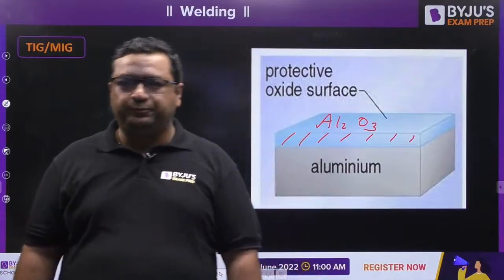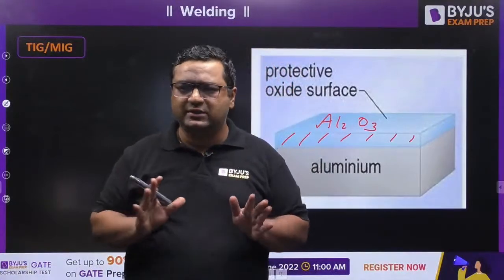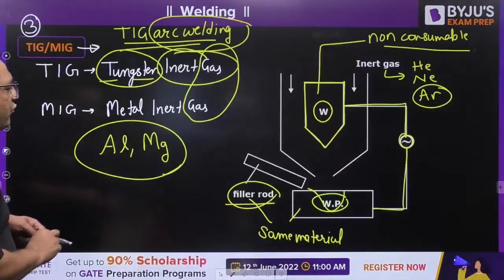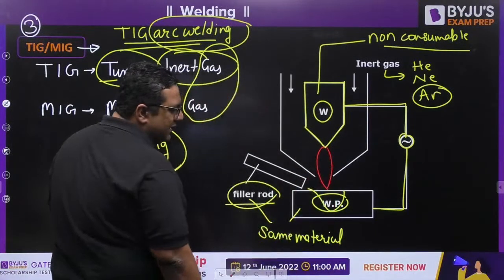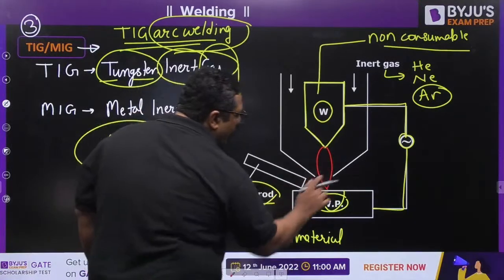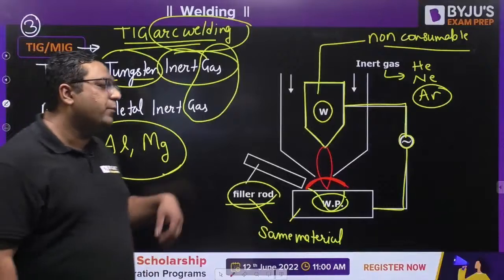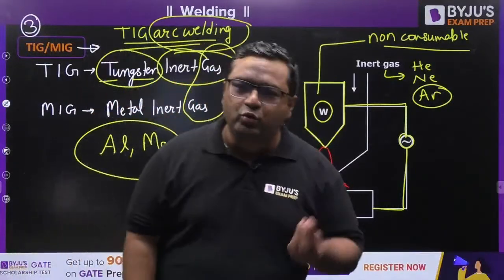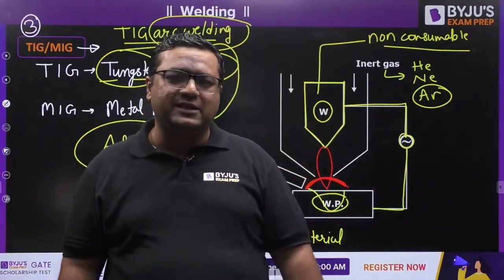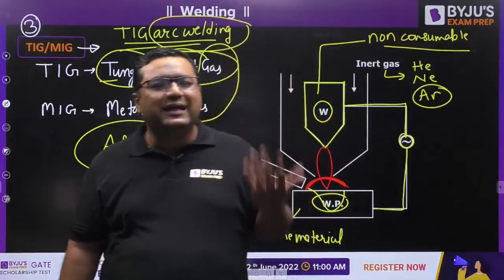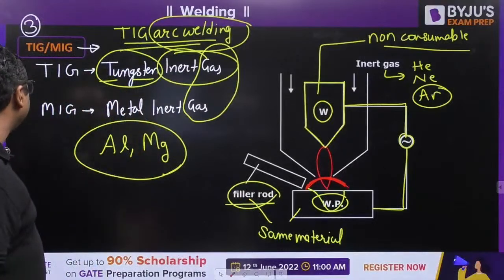Yes, Madhuvamshi, that's why I said inert gas will be performing two functions. One is it will keep the arc concentrated like this. Second, inert gas will avoid the contact of molten metal with the air. But my dear, for providing alloy content, you need to put some powder of flux if you really want to give some alloy content for such cases. But here we do not need alloy content. I am telling you about that, so just let me complete. You will know the reason behind that.